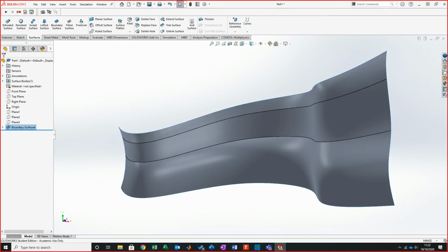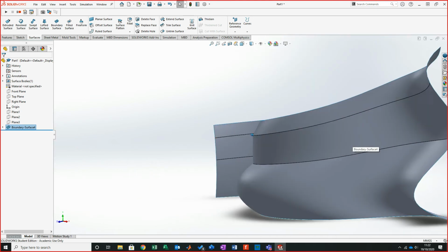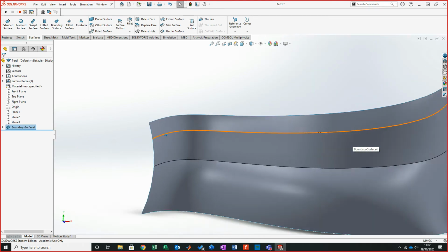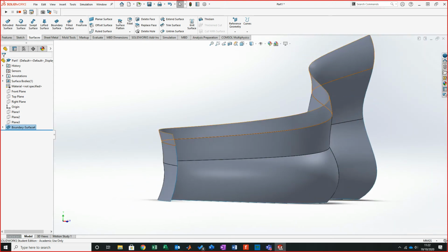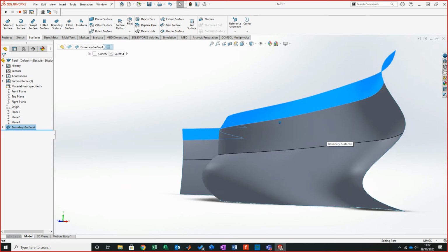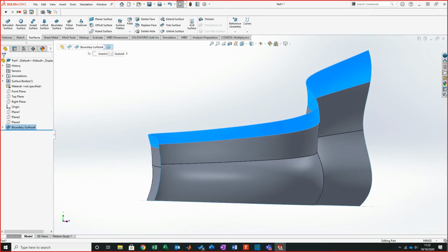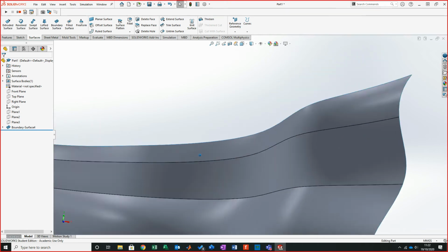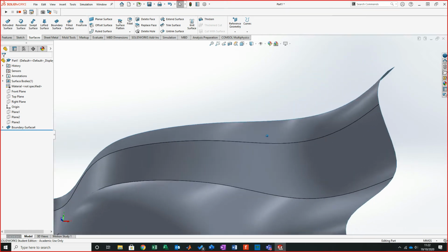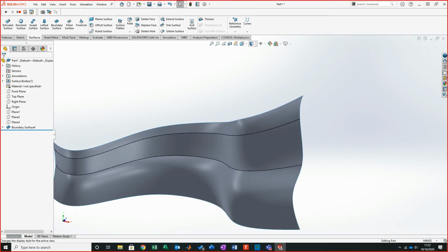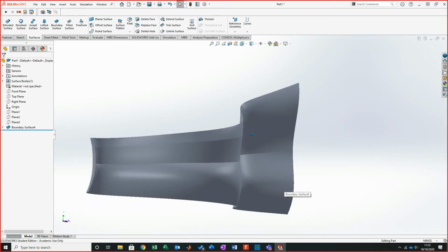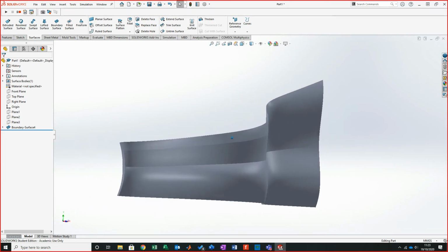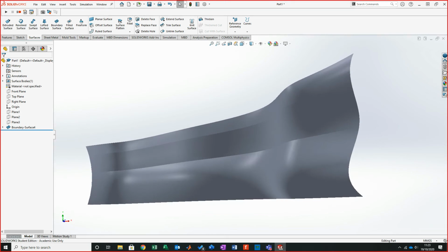I'm just really messing with the system right now. But you can see there, what it does is it will try and bring that edge in, knowing that there's going to be a split across it. The only real way to control that is by splitting entities. This is essentially what we did on the advanced lofting. So if I come up to the upper one here, you can see it flows across, but then I'll just turn off my edging to see how it would look in more of a realistic example. See there, we've still got that edge, and if you are wanting to be clear about how this thing would be produced and after it was produced.